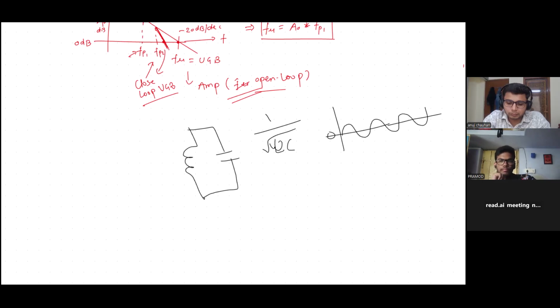Oscillations are coming. I am asking why the oscillations are coming, meaning what is the reason for oscillations? Let us assume no internal resistance. Initially, I have charged the capacitor or inductor, whatever. You can take anything. So I have charged the capacitor, or inductor, up to some value. When we connect the parallel network, it will go into oscillations.